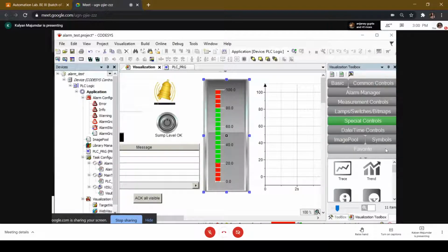So in order to draw the attention of the process operator, the plant operator, the factory operator, you're using color animation, because the minute he sees that this level has changed in color, he immediately knows something is wrong here. It's either too high or too low. Something corrective needs to be done. So how do you add color animation? That is the only point that I want to say, because the rest of it you already know.